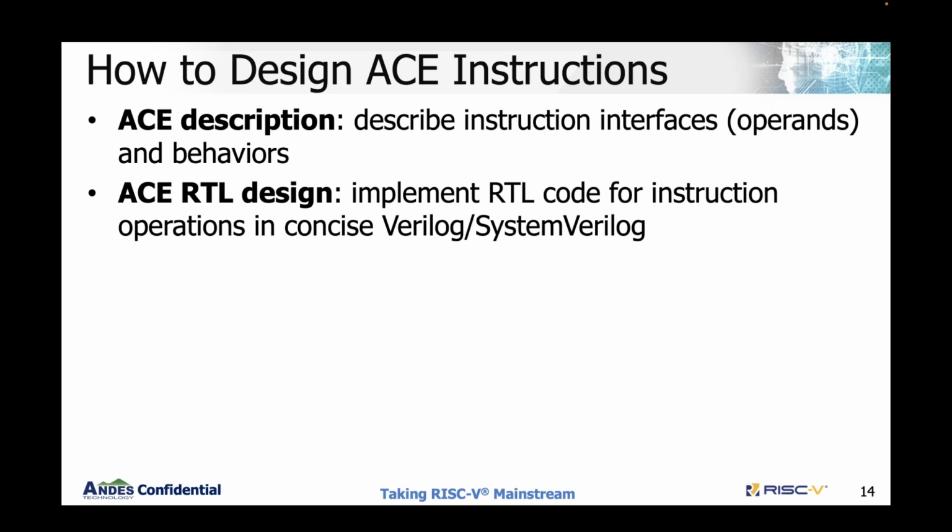In order to design the ACE instruction, you need to have an ACE description, which describes the instruction interface and behavior. And also you need to implement RTL code for the instruction operations in concise Verilog or SystemVerilog format.